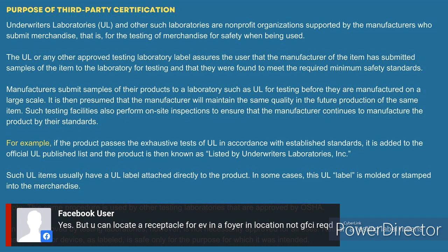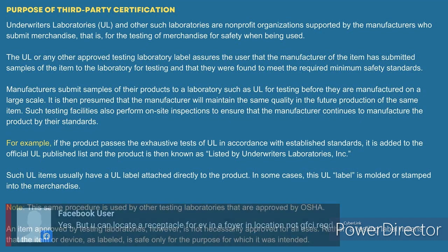Yeah. So he's saying that if you locate it in the foyer, GFCI is not required. Why would you put it in the foyer? I mean, I'd put it out in the garage. I don't know why you'd put it in the foyer.